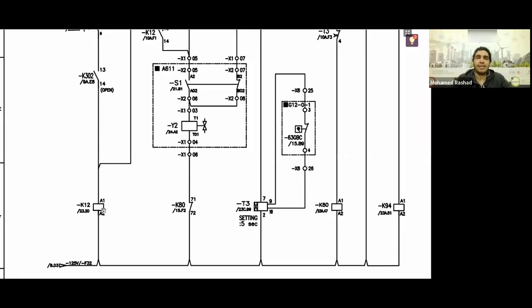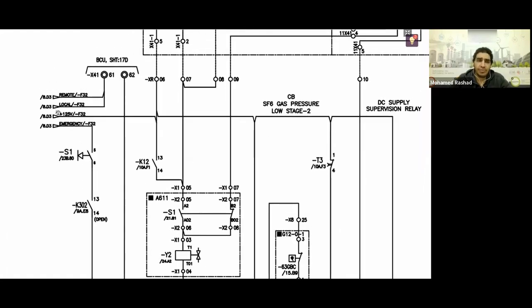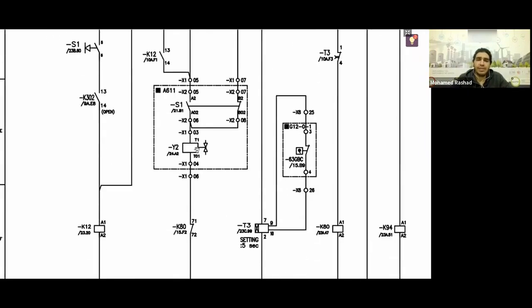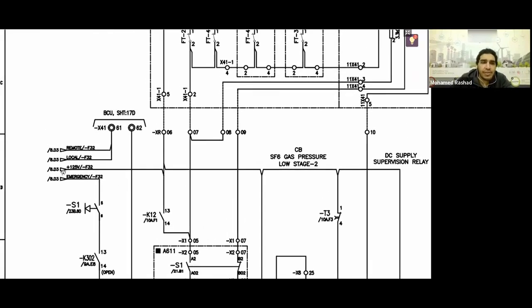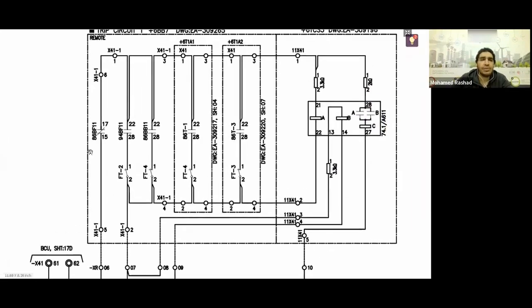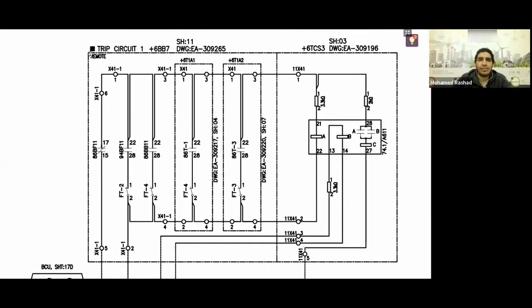Here, the cutoff switch is activated. This cutoff switch then comes to the positive in my circuit, passes through the cutoff switch, and this cutoff switch goes to trip the breaker. All right, great. See the trip, all of this, here it is before it, one is open, one is closed. Okay, look at the DC. Here it went from here to that big box, which is set up here as a remote. It's labeled as a remote panel, meaning it's going to the remote panel.